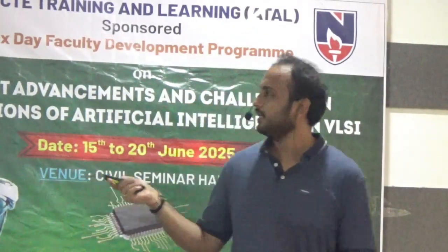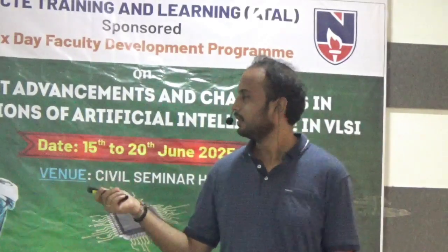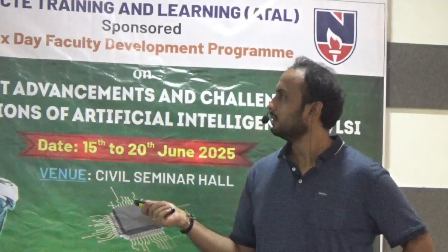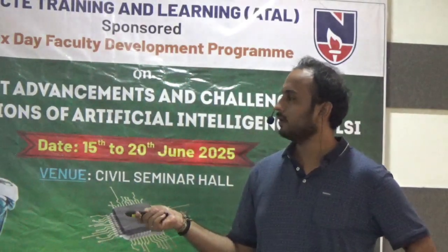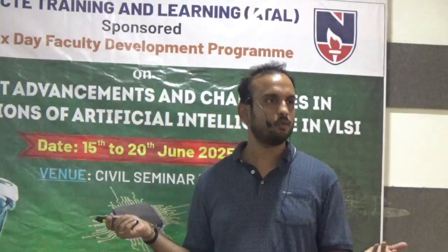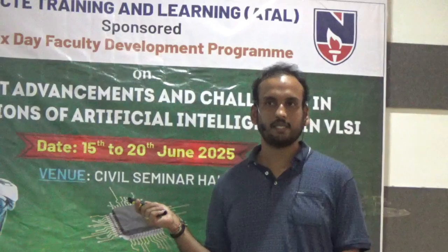So as an RF designer, I will be happy to use 20 nanometer technology because it gives me a very high FT max. And the analog designer always chooses something like 10 micrometer, because we don't want to see channel length modulation or velocity saturation effects.